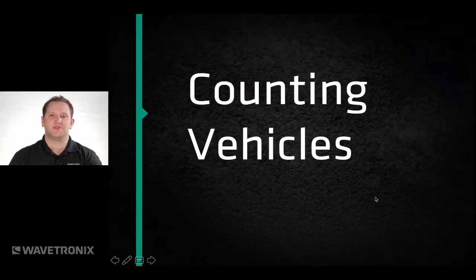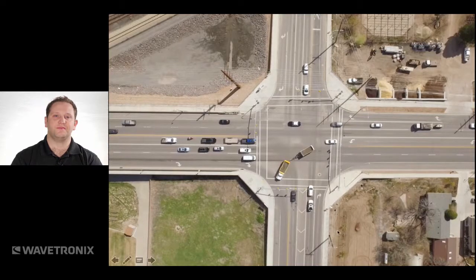So the next application we're going to talk a little bit about now is counting vehicles. Intersection counts are a key component of accurate timing in most systems. The SmartSensor Matrix allows you to get vehicle counts in individual lanes. We typically put the counting zones just in front of the stop bar. So you can see there on the image where we suggest you put the intersection detection zones. I'll show you how to configure them here.